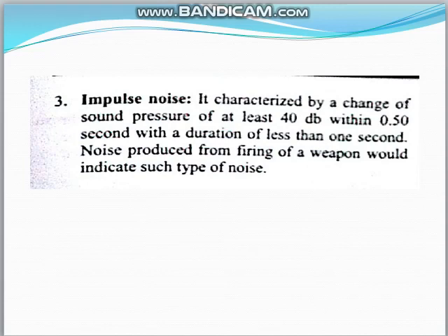Generally, this noise pollution can be prevented by taking some measures for effective control. One is the design of doors and windows. Generally, excellent sound insulation is obtained by constructing glazed windows with double or triple planes of glass. Okay, by constructing glazed windows with a double plane of glass, we can effectively control noise pollution. Okay, one is the design of doors and windows, and the second one is enclosures. So generally we have to provide enclosures, shields and barriers so that some of the sound waves are cut off from propagating. Okay, third one, planting of trees. Generally the presence of trees acts as noise barriers. Okay, so these are some of the effective measures required to effectively control noise pollution.